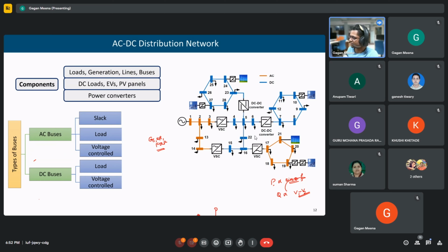In the distribution system earlier there were no converters, only simple loads and induction motors. But now and in future, because of smart grid, because of interconnection of so many different types of distributed energy resources, and even DC microgrid or AC/DC hybrid microgrid at particular buses, the methods which we were using for power flow studies of distribution system also need to be changed.